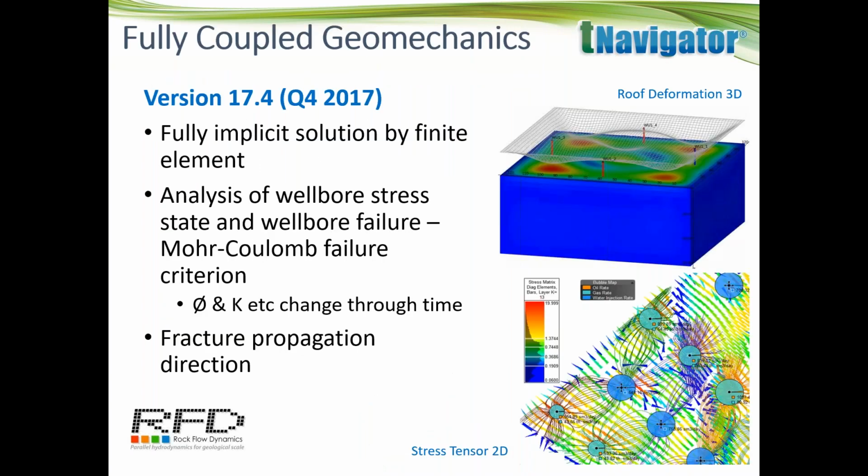Another development, this is actually something we are quite excited about, and we find that it is pretty unique in the world of reservoir simulation, is the coupled 3D geomechanics. So now we have the ability to solve the finite element elasticity equations along with the fluid flow equations in one system. So this translates into being able to see how your reservoir rock behavior affects the fluid flow and vice versa. So the applications for this could be, first of all, you can localize the potential damage zone within the formation.